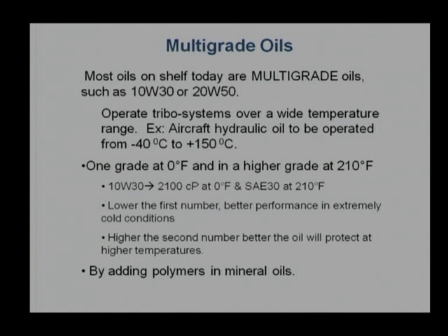The question comes, how to make this? Should I bring two oils, SAE10 and SAE30, okay, 50% of SAE10, 50% of SAE30, mix it, and use it? Does that work? Or should we use 30% of SAE10 and 70% of SAE50? In reality, in practice, this kind of approach does not work. Simple mixing will not work. There are a number of methods, but the most popular method is adding polymers, adding additives in mineral oil. So, we add polymers in mineral oil to increase its temperature range.